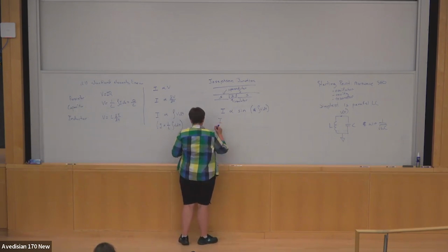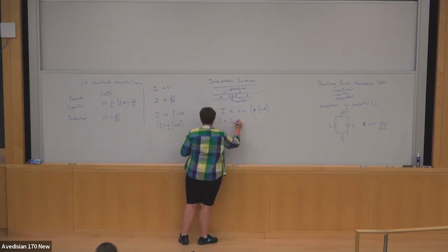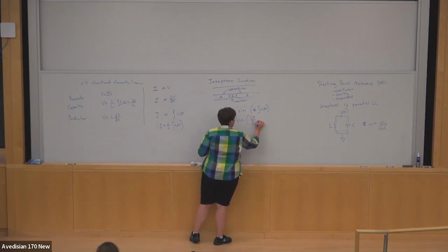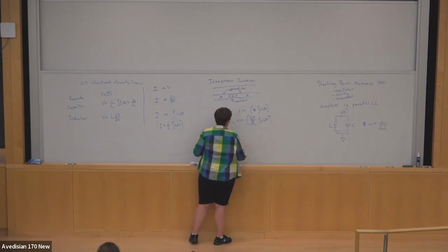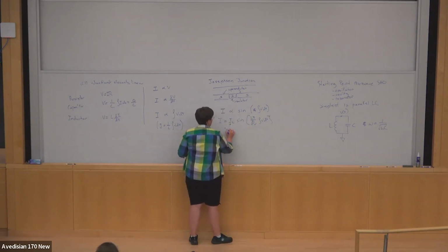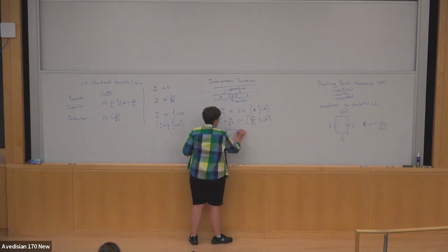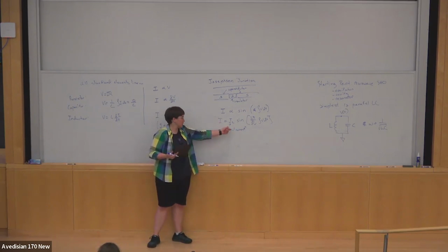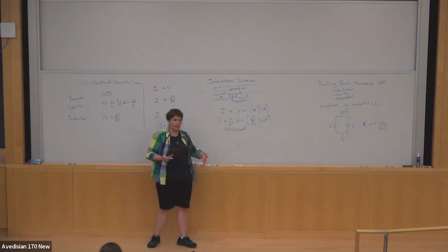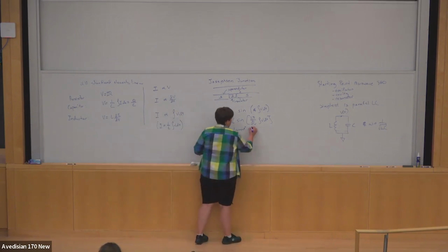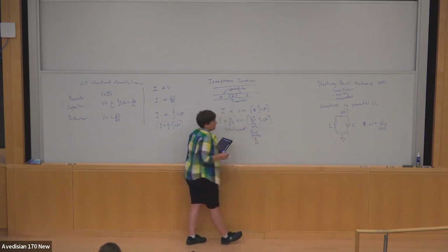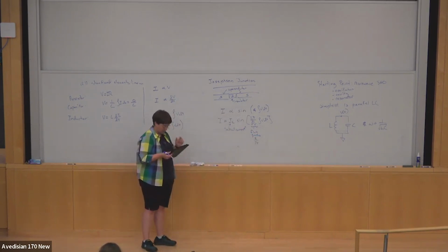And so the actual formula is I equals I_C sine of 2 pi over phi naught, the integral of v dt. This is something which is called the critical current. You can't actually have a current in a Josephson junction larger than the critical current. So if you try to pass that value, it just craps out. This is the flux quantum, h bar over 2e. It's 2e because in superconductors, the electrons come in pairs.